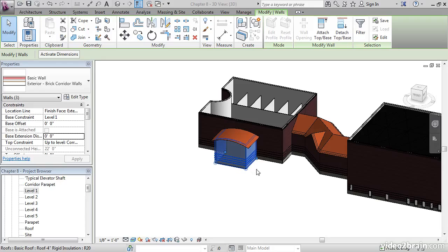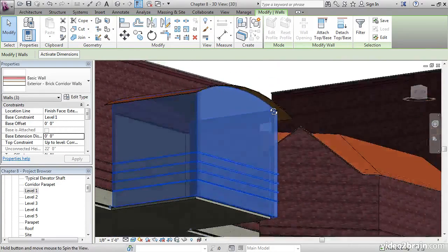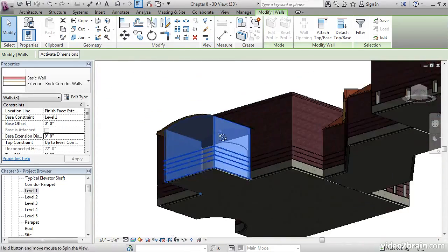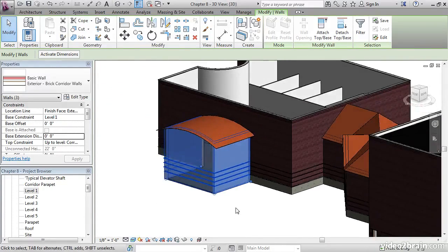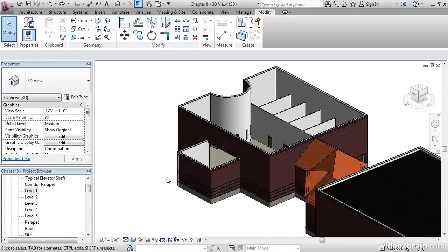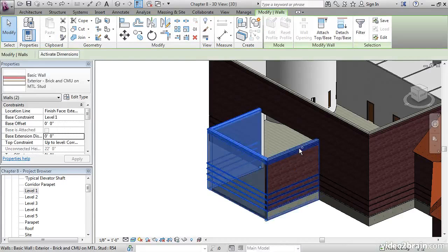As you can see from this example, we have a little curved roof. Nothing great, but kind of cool nonetheless. I don't know how else we do it in traditional method other than creating a roof by extrusion. First thing I'd like to do is go to a 3D view. Let's zoom in on this south addition to the west wing. Holding down the Control key, let's select the three walls.